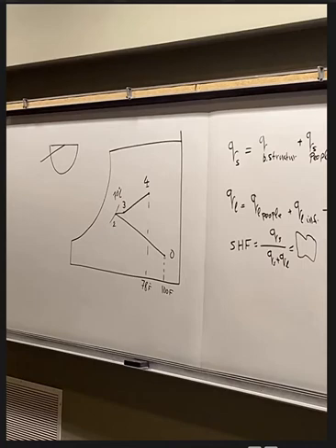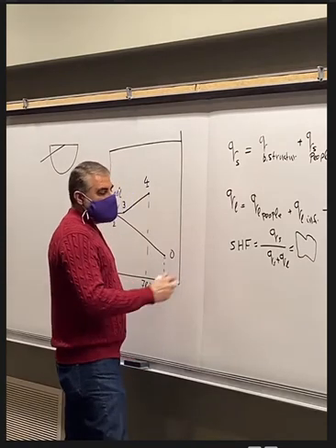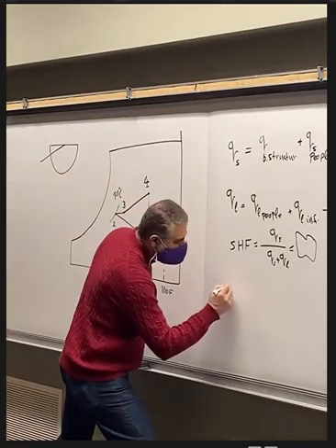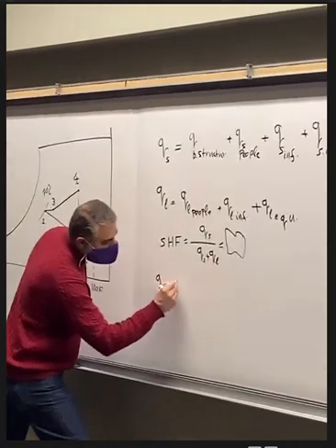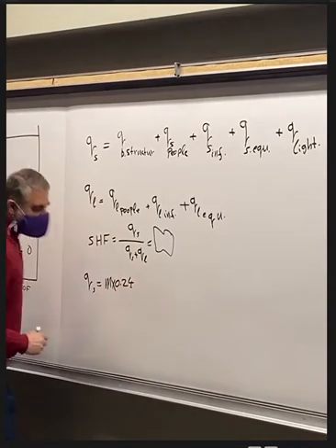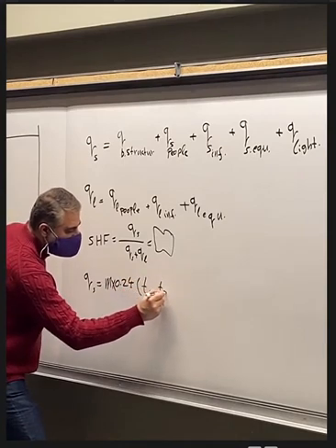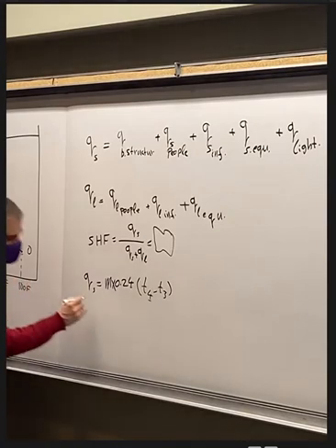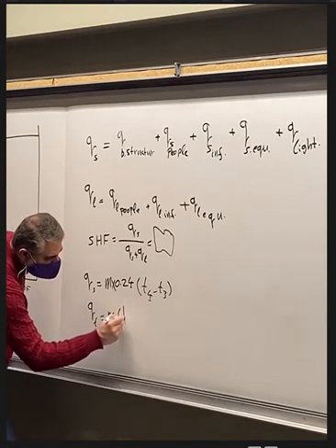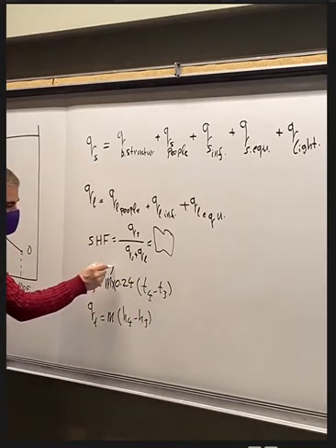The amount of supply air: we know QS for the cooling load, and we know T3 and T4. So that means QS equal to M multiplied by 0.24, which is the specific heat for air, multiplied by T4 minus T3. Or we can write Q total equal to mass flow rate multiplied by H4 minus H3. And any of these equations will give you M.